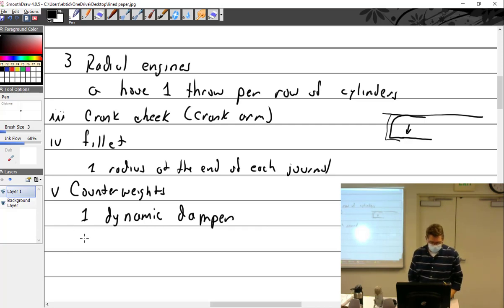I should finish that story. There was more to it. So this particular 182, 182s have a belt-driven alternator off the back. And he was bringing it into the shop because it had thrown the second alternator belt. They brought it in the shop, put a brand new alternator belt on. He took it out, he's flying IFR, he's in the clouds, and he gets an alternator failure and brings it back in, and it threw the belt.